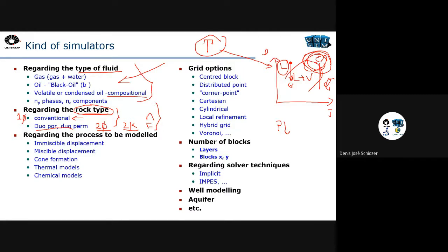The most important part of the solid movement in the reservoir for us is if it happens close to the well. Here, for example, you have a porous media, and the porous media has a porosity, and if the solid is moving through the well and getting here and changing porosity and changing permeability, then this is important for us for reservoir simulations. But instead of putting this solid movement in the equations, we can write this in the well equations, okay? I don't know why you're so concerned about solid movement, but for us, this is not important, okay?